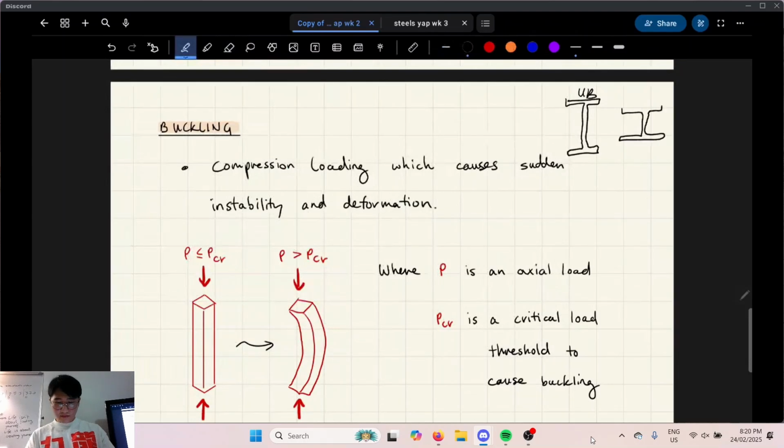So what's different? The web is longer, and usually the flanges are less wide. Why do you reckon that is for beams and columns? Because the universal beam is supposed to take on shear, and columns not really much. More bending, yeah, shear a little bit.